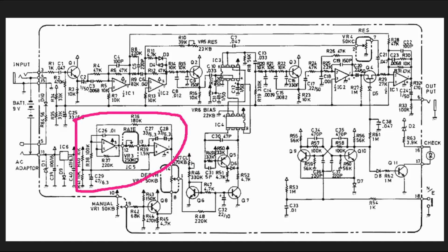And once we have our LFO, we have a depth control on the outside. This is just another voltage divider control. And this voltage divider control comes out over to this point. But before we take a quick look there, there's another external control that is chained with it, and it is this manual knob.